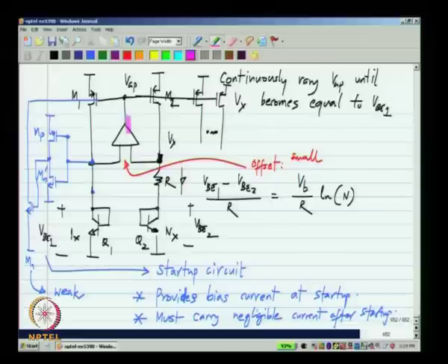Now, one of the other things to be considered is that unlike in many other circuits, in this circuit the op amp has feedback to both of the input terminals. So, we have to figure out the signs of the op amp, so that the overall action is of negative feedback, and that can be done very easily just as usual by breaking the loop and applying a test voltage and so on.